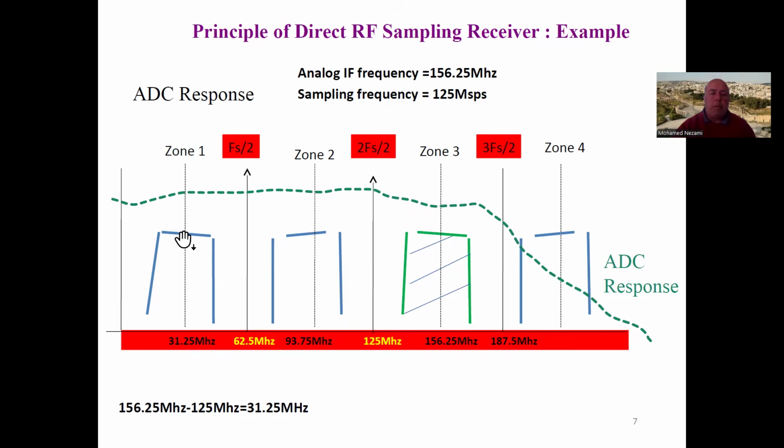So you can pick either this or this or this, and keep track that whichever one you pick, you need to be aware of the spectral inversion. You can spectrally invert any signal via very minimal mathematical operations, like sign inversion of one of the I and the Q, or swapping them. You can look that up; we may go into it in the future. It's spectral inversion of a signal using numerical methods in the DSP domain.